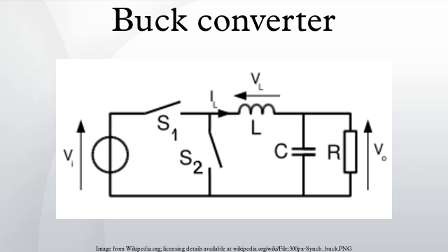When the switch is opened, the diode is forward biased. The voltage across the inductor is V_L = -V_o. Current I_L decreases. The energy stored in inductor L is E = 1/2 L I_L^2. Therefore, it can be seen that the energy stored in L increases during on time and then decreases during the off state. L is used to transfer energy from the input to the output of the converter.